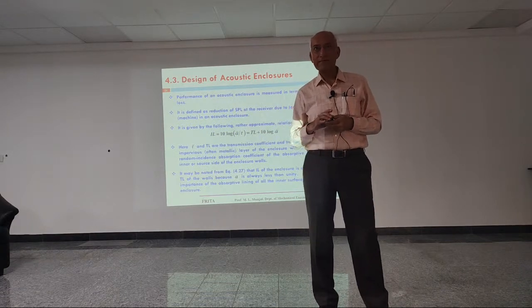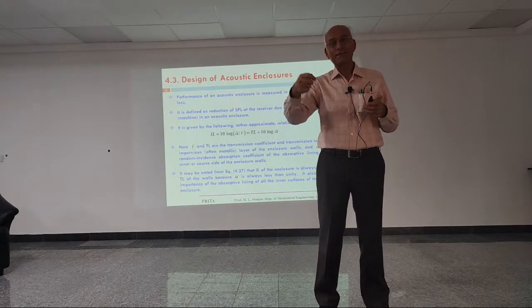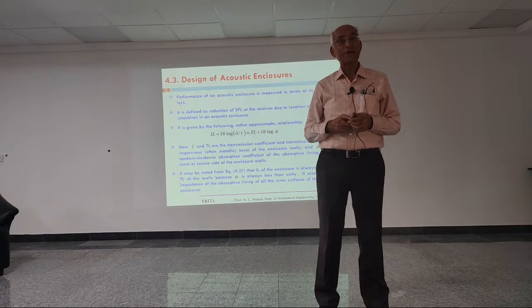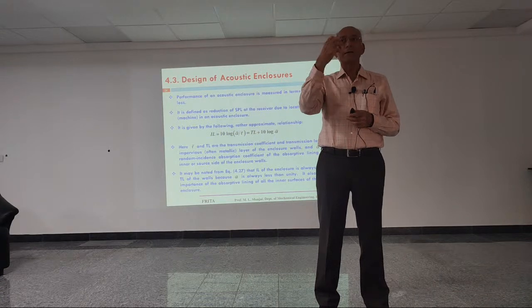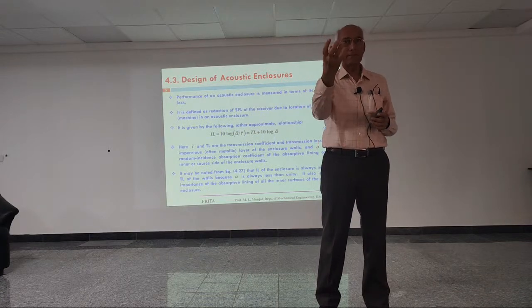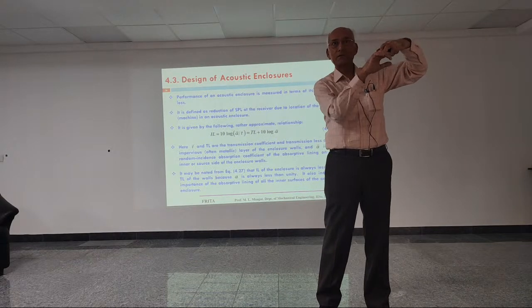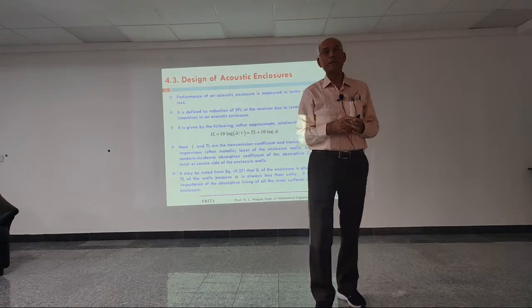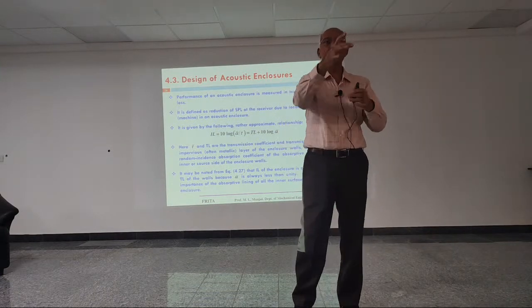So essentially, for example, I will go for, let's say, belts, etc. But belt, of course, has one very good advantage that it gives me damping. It also increases the surface area I was talking about. So therefore, it is much less noisy and all that. But then it has other problems also, because suddenly something has to change.